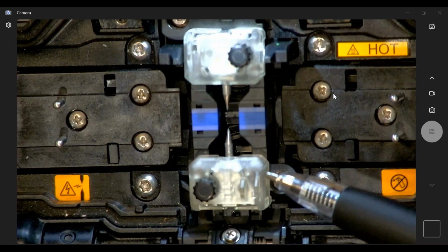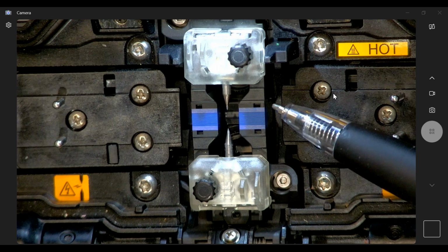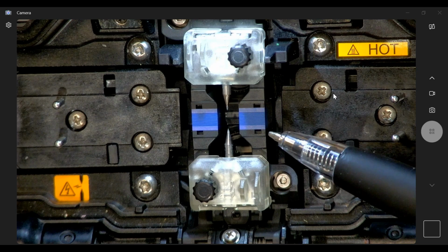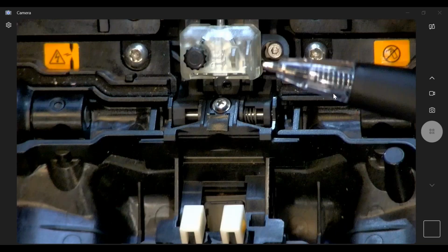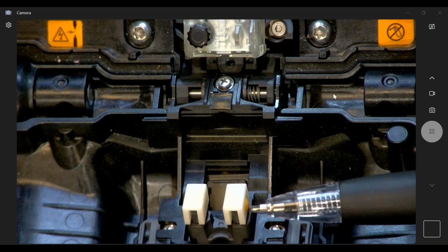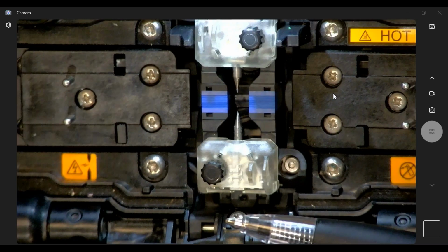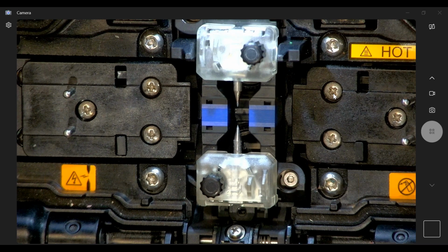And I will point out the V grooves. Here again, these are 12 individual V grooves. This is a fixed V groove system. And if I open the wind protector and slightly bend it forward, I will slide the splicer up a little bit and actually show you the V groove chip clamps. This is the mechanism that comes over top of the V grooves and will locate that fiber by that 3-point alignment that we discussed earlier.